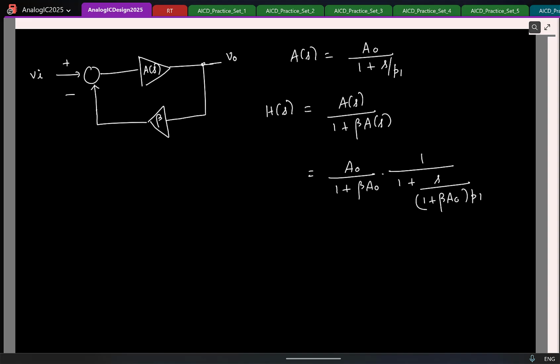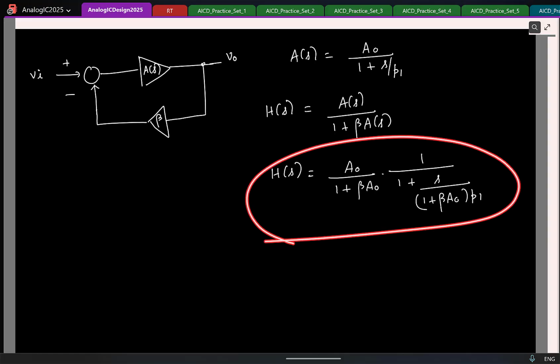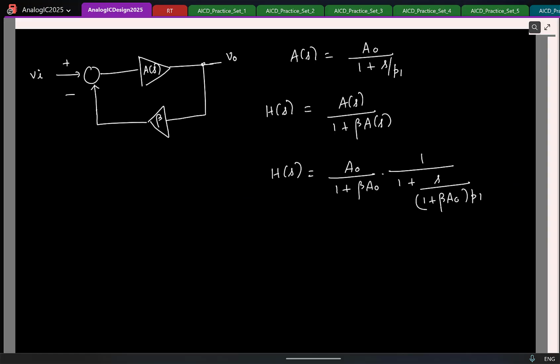So tell me now, this is the closed loop transfer function I get if I put my first order system in negative feedback, right? If I tell you that this is the closed loop transfer function, tell me if this system is stable or unstable. How can you tell if a system is stable or unstable? The pole should be where? In the left half of? So do you think the pole here is in the left half of S plane? Yes? Why?